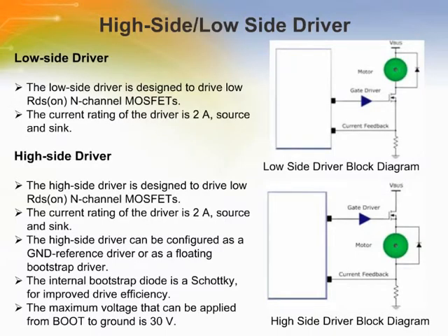High-side gate drivers are used to drive a MOSFET or IGBT that is connected to the positive supply and is not ground referenced but is floating. High-side drivers are more complicated than low-side drivers because of the required voltage translation to the supply and because it's more difficult to turn off a floating transistor. It refers to how you drive a load. High side means your switch is between the plus power and the load. Low side means that the switch is between the load and negative power.